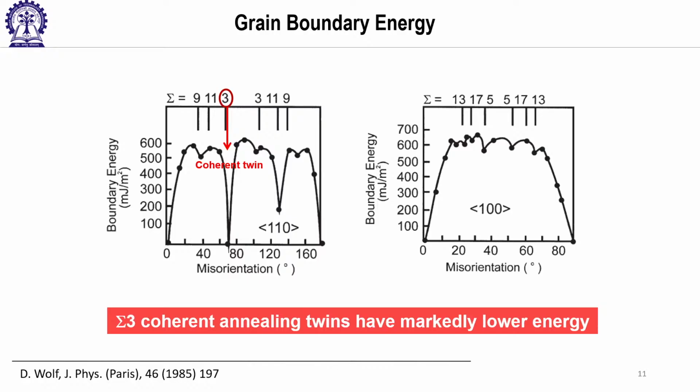Normally, there are two kinds of twin boundaries typically, coherent twin boundaries and incoherent twin boundaries. Typically, coherent twin boundaries will not show so much deviation. Incoherent twin boundaries will show some deviation, but definitely not close to 8.67 degrees. So if your boundaries are showing deviation of more than 4 degrees, then definitely these are typically not CSL boundaries, although the criteria allows them to be considered CSL boundaries. So more and more boundaries oriented perfectly towards CSL is always better.